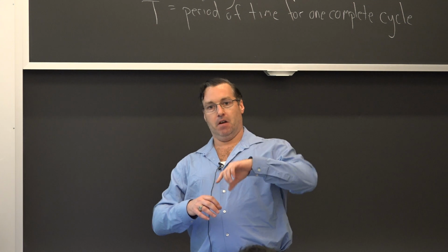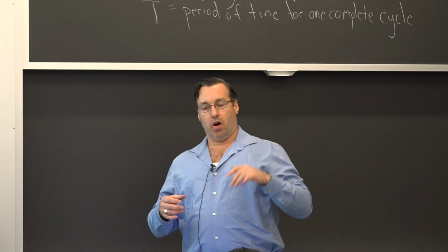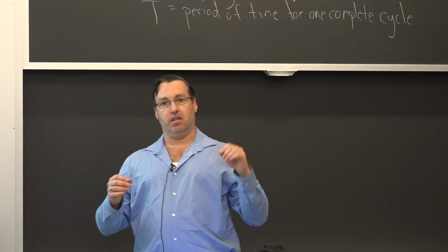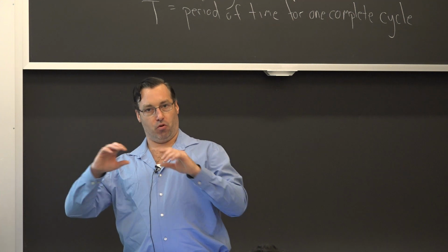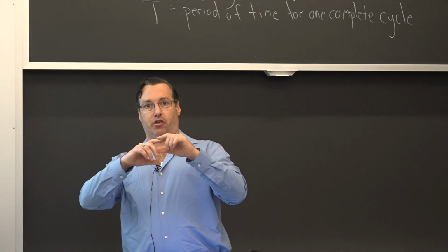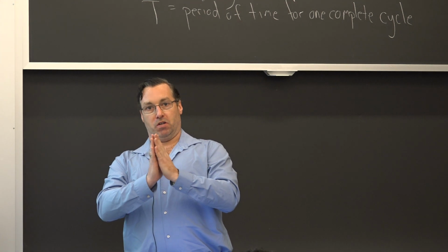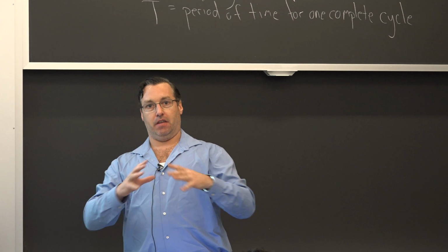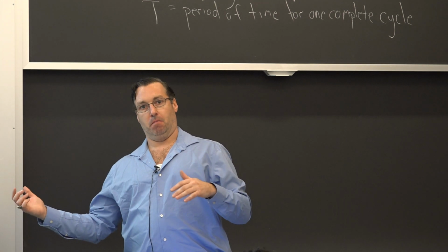You can actually have something similar to a dog bone tensile specimen. And what I've seen on some samples is they actually will insert either a borescope camera or some small type of camera, and then they will zoom in on that notch. So what they can actually do is map and track with respect to how many cycles that they've put onto that sample to try to correlate to different modes.